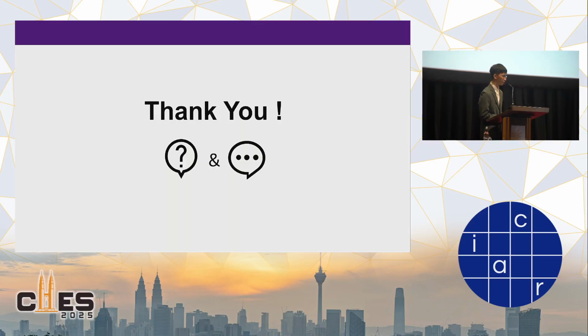And as the transfer function from the VCO to the output acts as a high-pass filter, since the noise power spectrum is shaped by the transfer function, it means the flicker noise of the VCO is suppressed. So we don't need to think much about the flicker noise of the VCO.